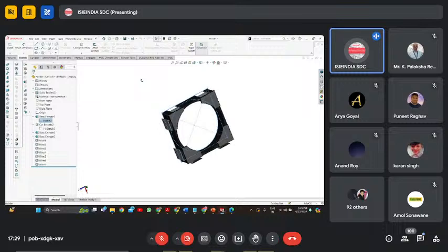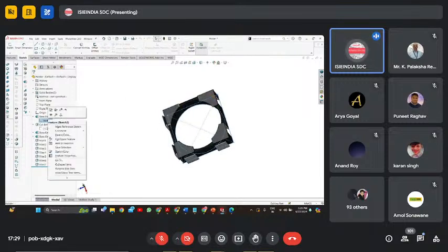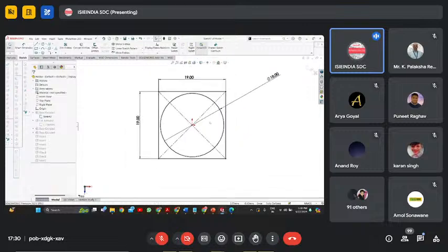To make the battery pack holder, first we decided what type of holder to use. Here I have used an interlocking battery pack holder, so that we can interlock it easily, and which is also easily available in the market, because we have to choose accordingly. The diameter of the cell is around 18, so I have taken 19 as the width so that there is a proper gap in the battery holder mold.